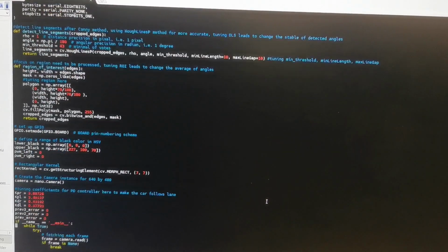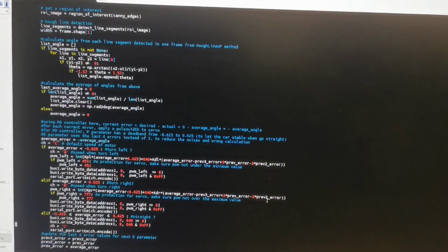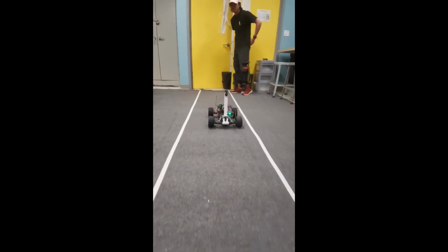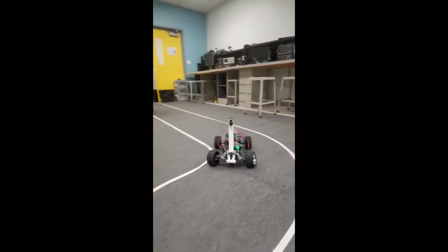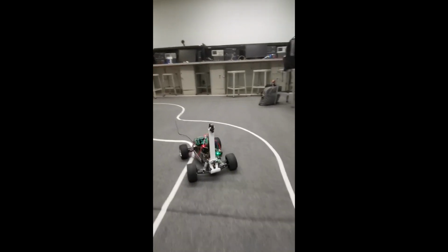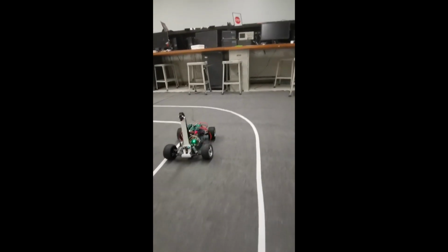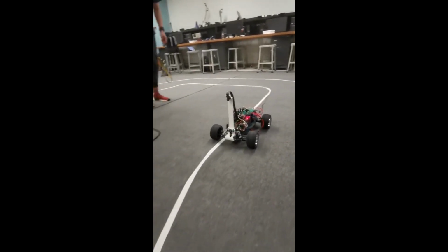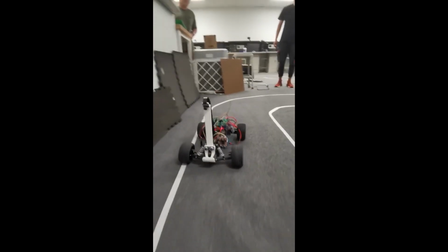Besides the hardware and software for the basic line following function, the two extra features, ultrasonic sensor and object detection, can also be improved to help the car navigate through complicated traffic situations. In our current design, the ultrasonic sensor's reading is not stable and accurate. This can be improved by adding an Arduino to run the ultrasonic sensor and output the reading to the OpenMV. The object detection can also be improved by feeding more pictures to the OpenMV to study. That's all we are going to present in the video.